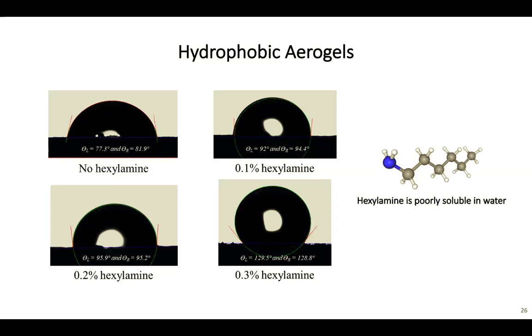And this is important: use as little hexylamine as possible, because at the end of the day, you should not cover the pores, the outer pores of the aerogel. Therefore, it might change the dynamic behavior. So that's why we stick to a very small amount of hexylamine.